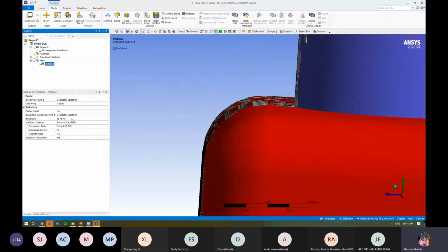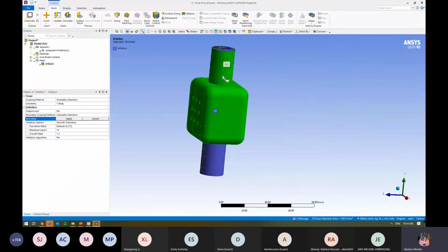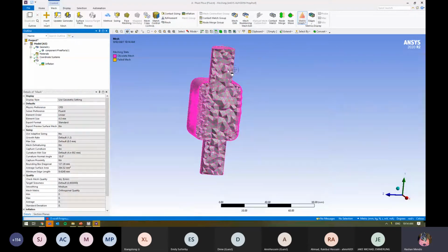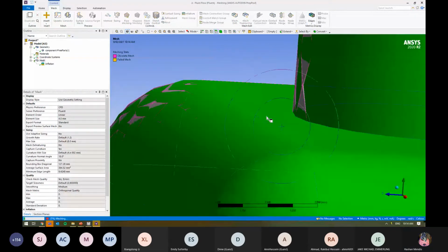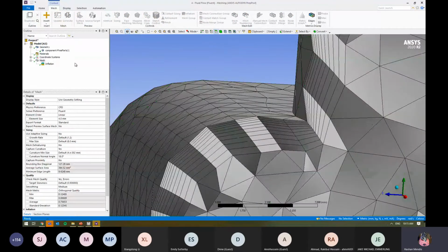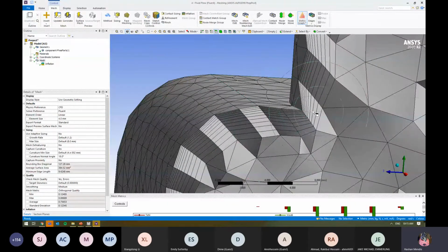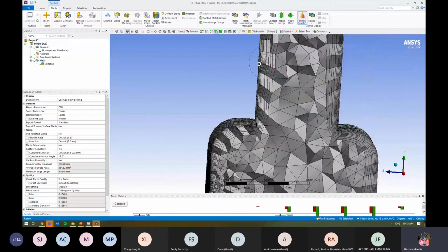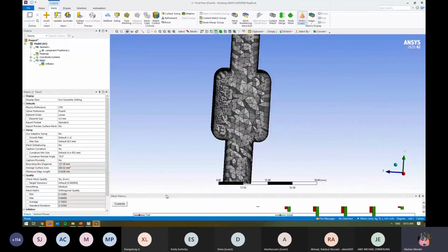If I wanted to, I could also add these two, right? And you'll notice around this region, right, we'll have better mesh quality because now instead of stair stepping, it's able to actually turn that corner and come around, and we've got mesh elements all the way up there.